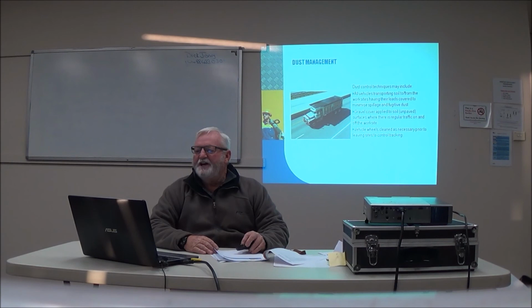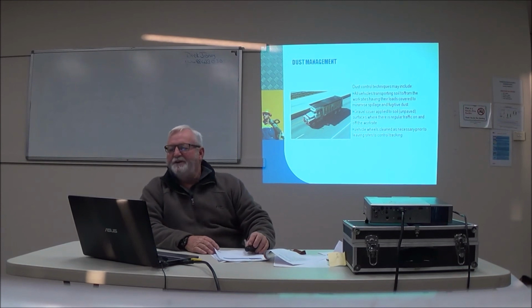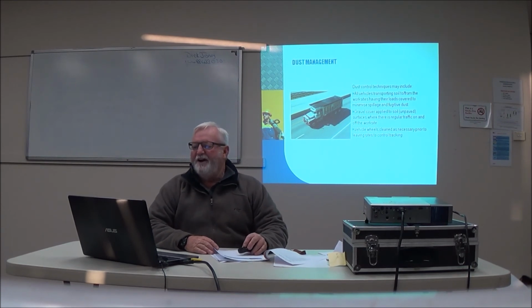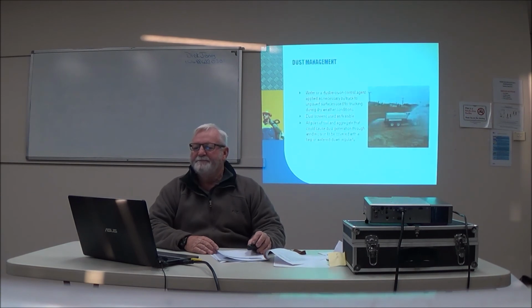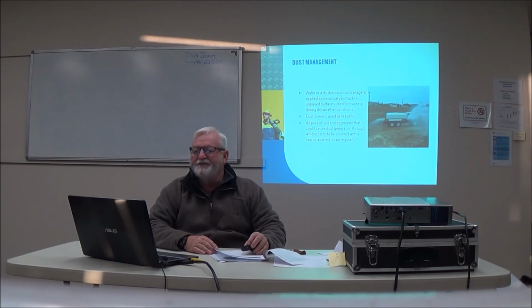Dust management. Dust control techniques may include all vehicles transporting soil to or from work sites having their loads covered to minimise spillage and fugitive dust. Gravel cover applied to soil on unpaved surfaces where there is traffic on and off the work site. Vehicle wheels cleaned as necessary prior to leaving work sites to control tracking. Water or a dust erosion control agent applied as necessary by truck to unpaved surfaces used for trucking during dry weather conditions. Dust screens used as feasible.